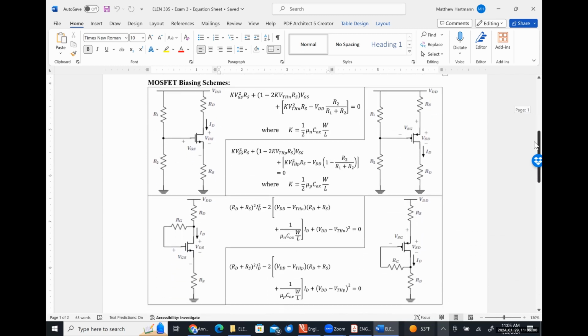And then if we scroll down here, I have the circuit diagram for the 4-resistor bias network. Up here are our relationships for the polynomial, but this is an older one. I'll go back and fix this to give you just the VGS equation and the VDS equation, only with channel length modulation neglected, because I can't make you work anything where channel length modulation is included.